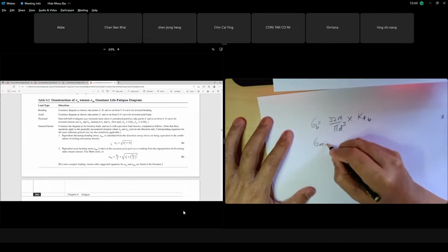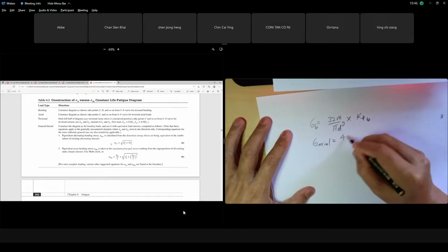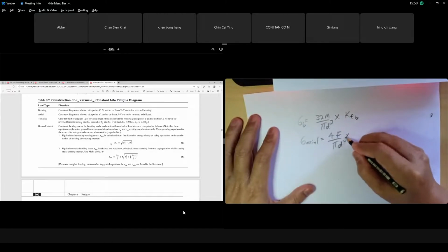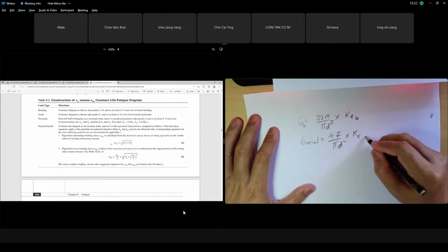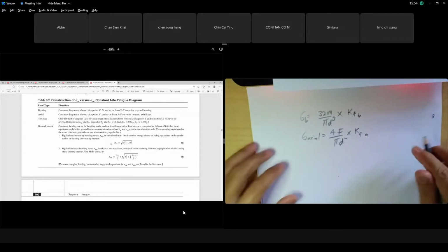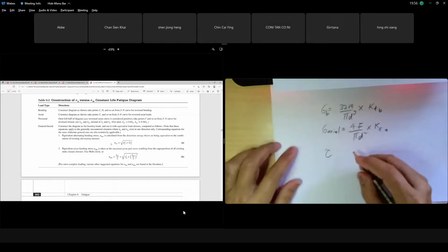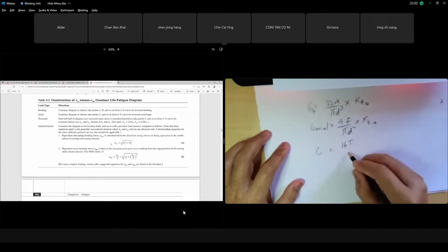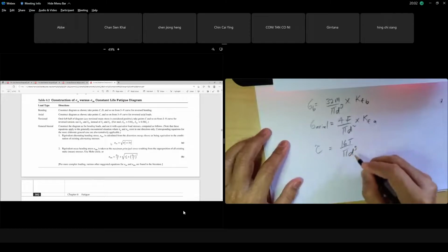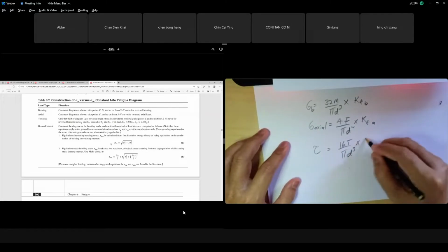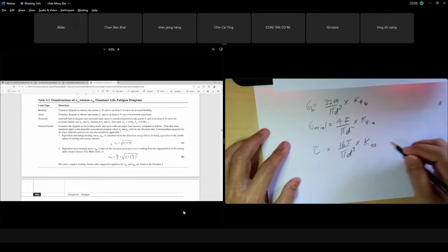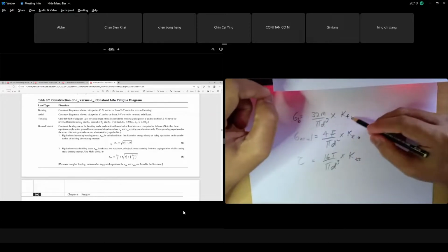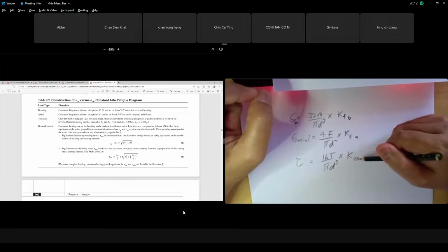Axial stress that you calculate, if you have axial stress on your shaft, F over pi d squared, the smaller diameter of your shaft, times the fatigue stress concentration factor based on axial. Torsional stress along your shaft, 16 T over pi d cubed of the smallest diameter of your shaft, times Kf based on torsion. So you have to apply this. So what is this Kf bending, Kf axial, Kf torsion?